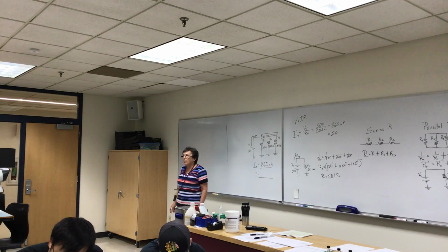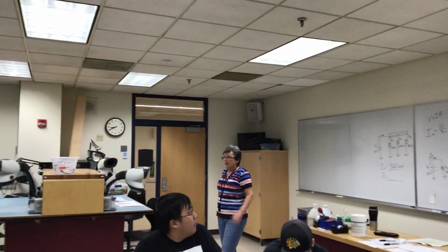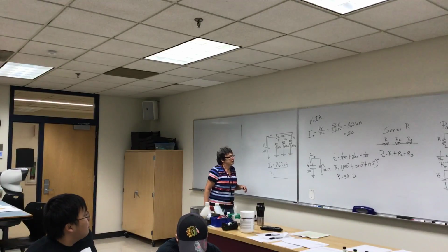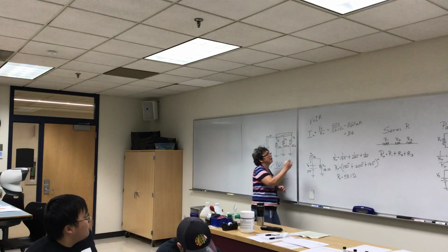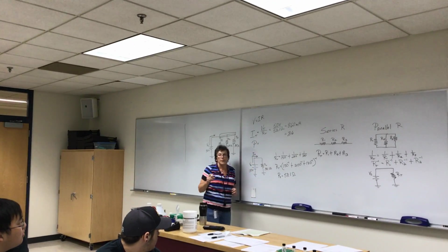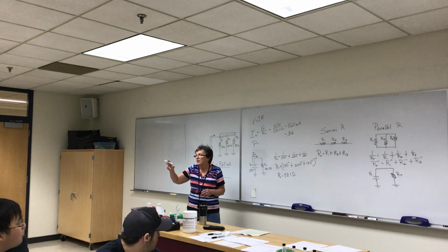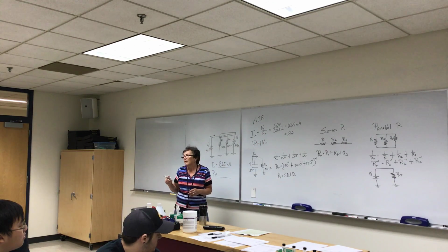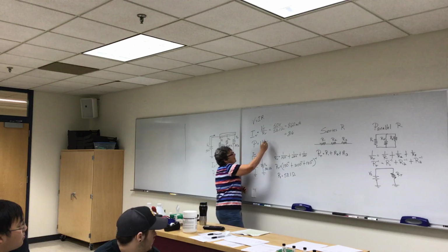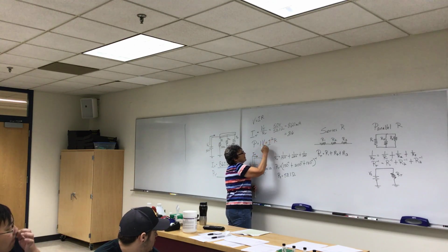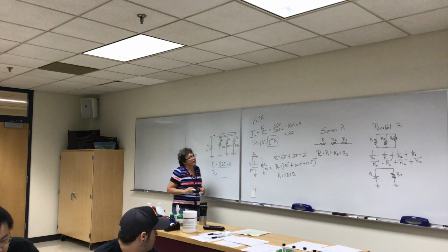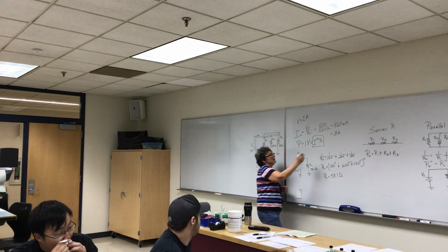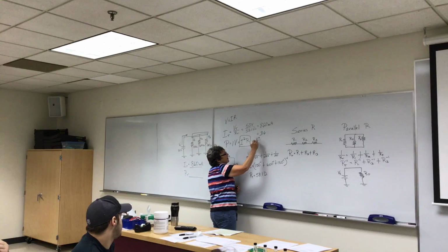How do we calculate our power total? I want two equations, with the information we have, that we can use to find our power. What two equations? Just give me two. P equals I times V. What's another one? I squared R. This one is used as commonly as that one. And then you could also do voltage squared divided by resistance. V squared over R.